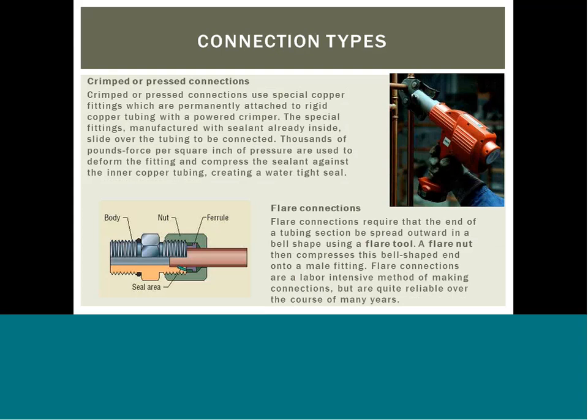The advantage of this method is that it should last as long as the tubing. It takes less time to complete than other methods. It is cleaner in both appearance and the materials used to make the connection, and no open flame is used during the connection process. The disadvantages are that the fittings used are harder to find and cost significantly more than